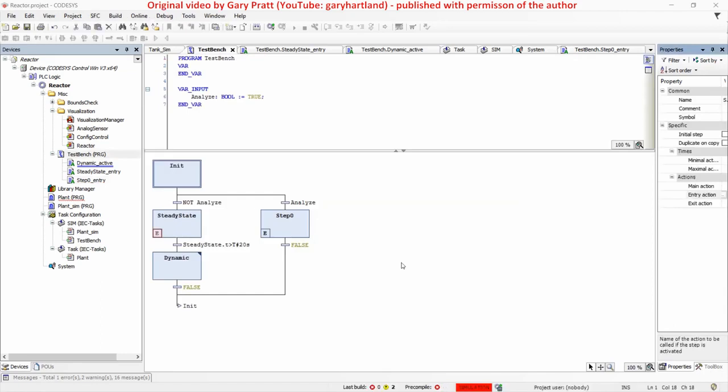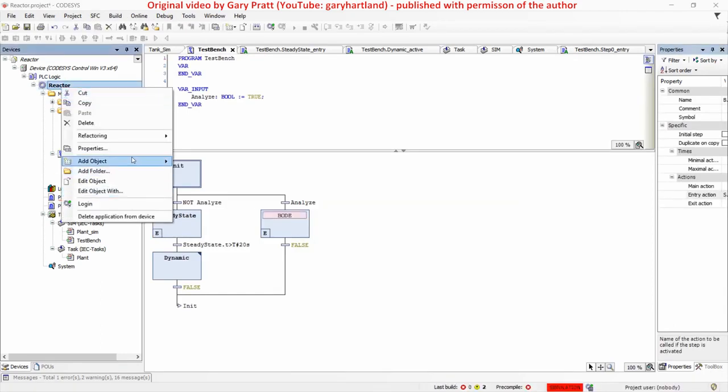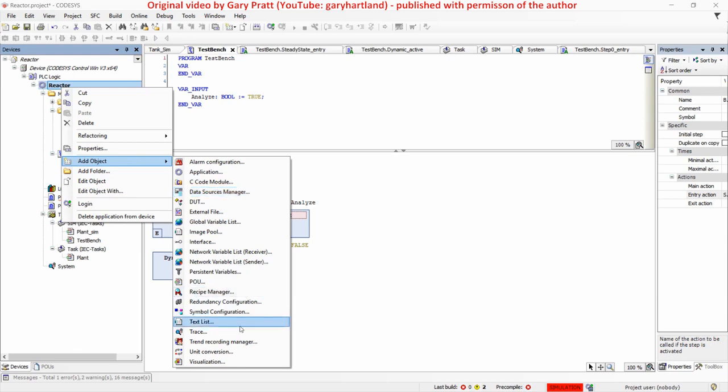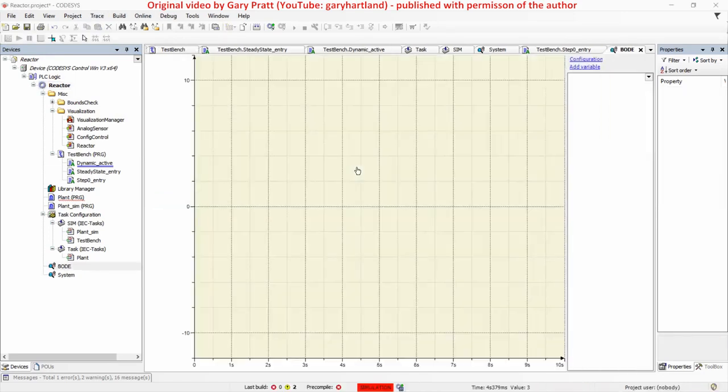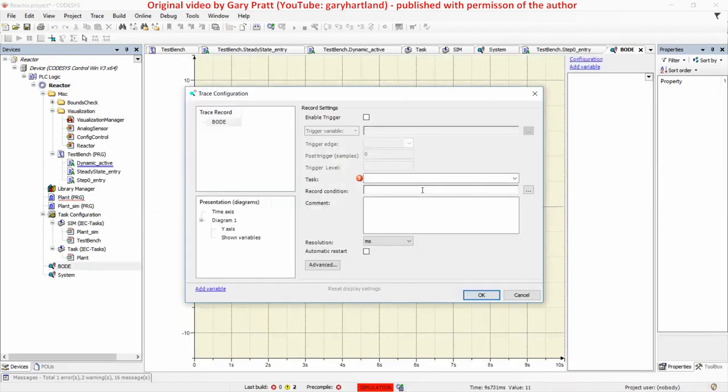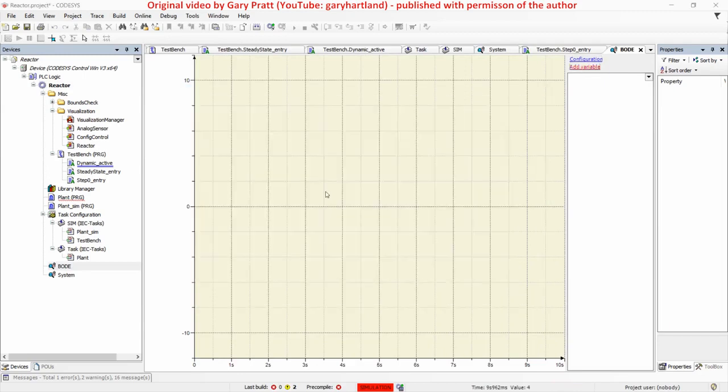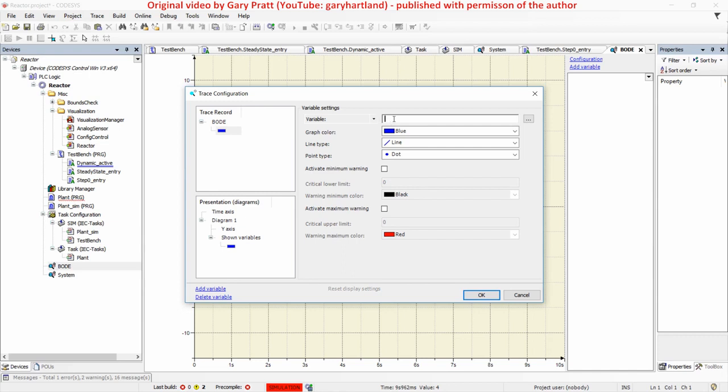We could look at the output of the analyzer in a CSV file it creates automatically, or from an Excel file via OPC UA, or we could just hook up another oscilloscope, and that's what we'll do. And we'll plot the frequency, the gain, and the phase.